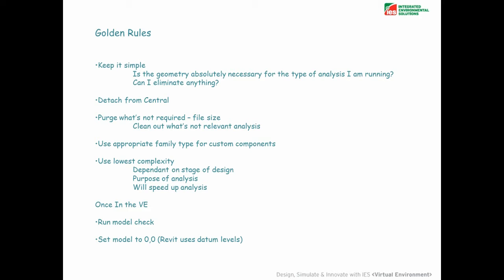The key one is to keep your geometry nice and simple, and, following the BIM process, try to get your early stage design out and export to an energy package to get the key data from your energy model to see which way your design is going to go. That is a big step to try and achieve. Obviously, the further down the line you go, as we discussed with that graph, the harder it is to impact any major design changes.